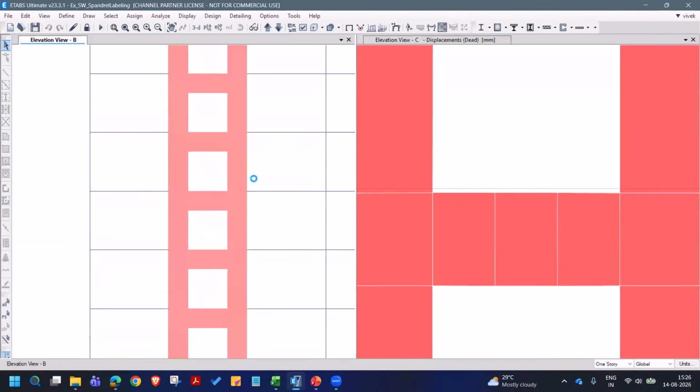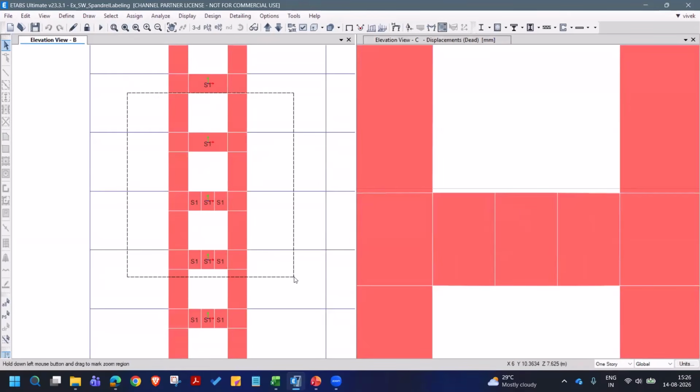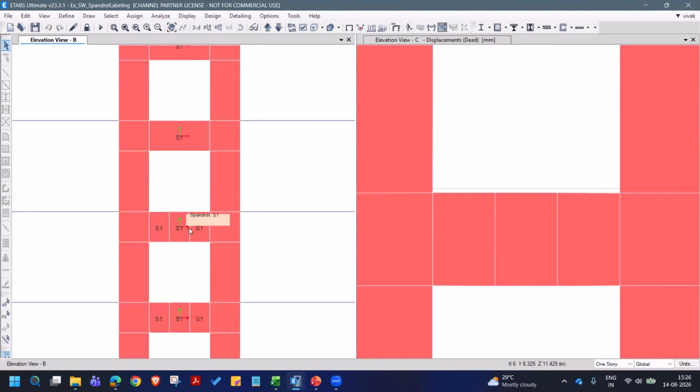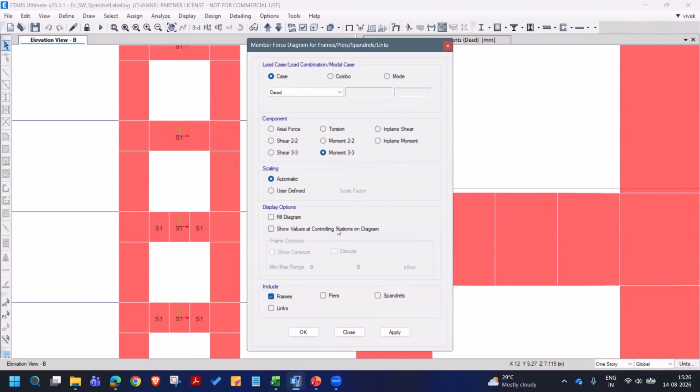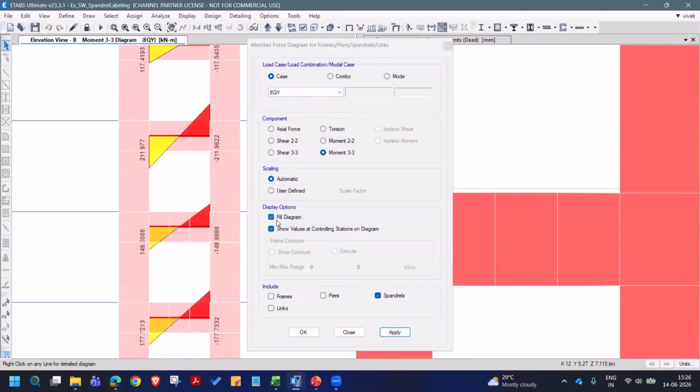You can see for this one, these are meshed elements with the same label and a single unmeshed one. If you go to the forces, you still see the same N forces, and the linear variation between these two is maintained for both meshed ones with the same label and the unmeshed one.